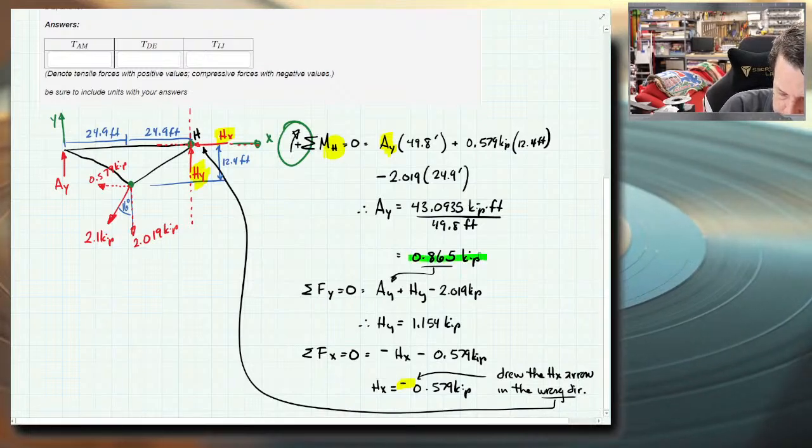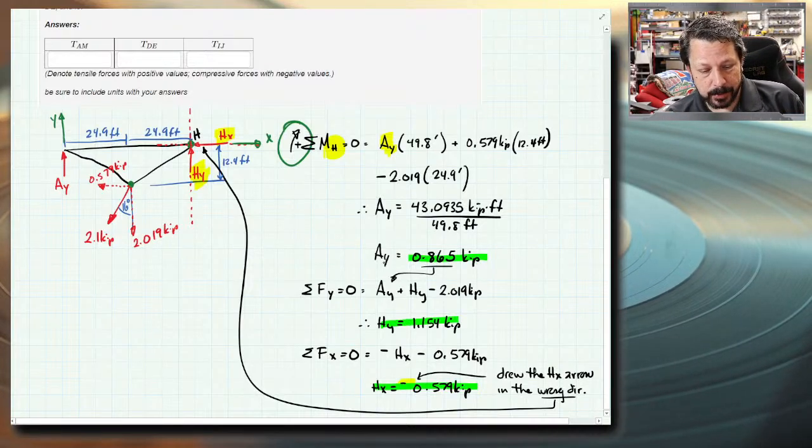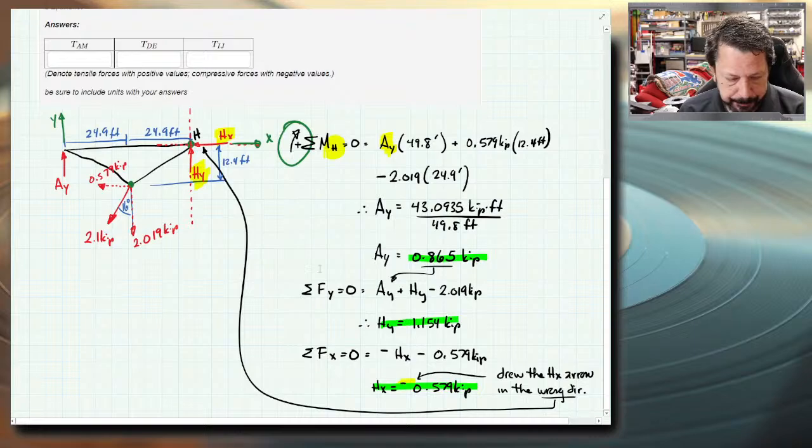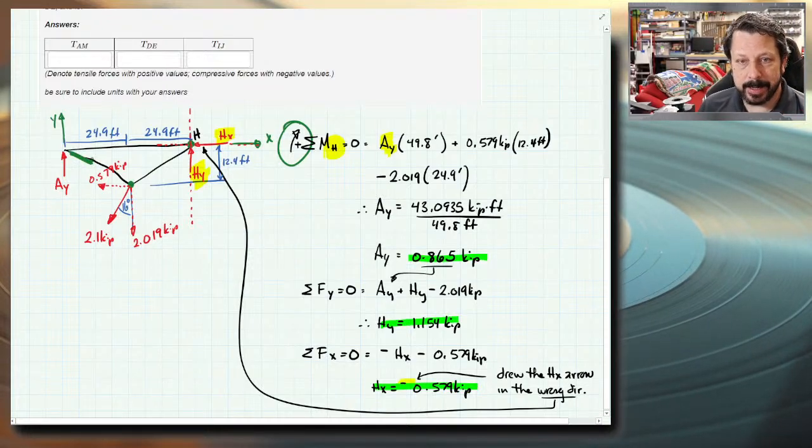So I've got my three external forces here. I've got AY, HY, and HX. And again, depending on what I was actually solving for, I may not need all of these. For instance, if I were just solving for AM, which is this piece, all I need is AY. I don't need HX and HY. I could just do method of joints at A once I get AY. So some of these problems are set up so that you don't necessarily...